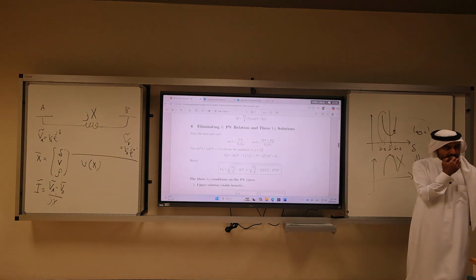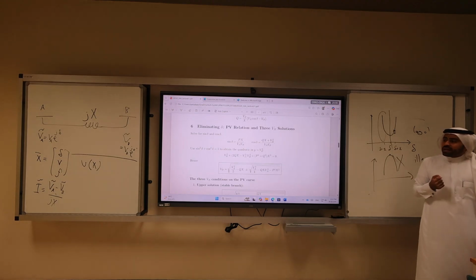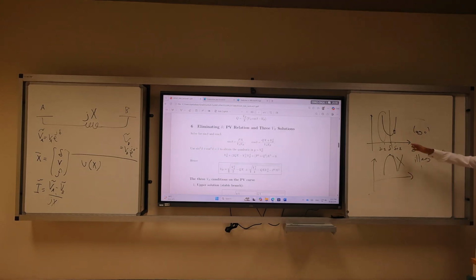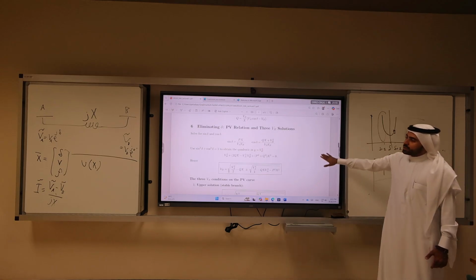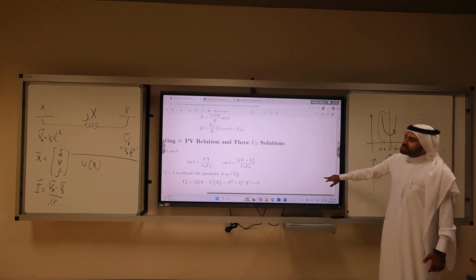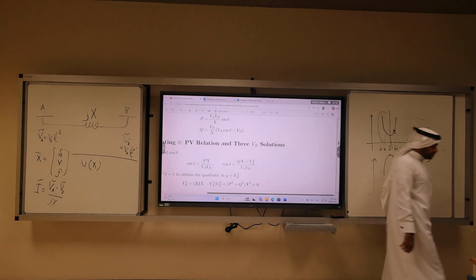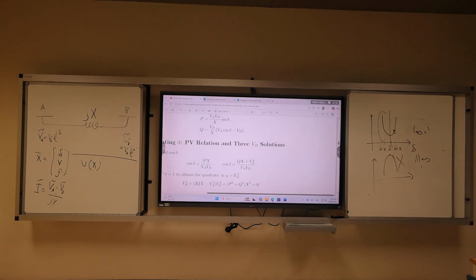Because sine 90 equals cosine. Well, if you operate above 90 degrees in this region, you still can go back to stability. But how can I answer this question? What is sine of 100? It starts having negative signs. Negative. So don't exceed 90. In power systems, there is no delta larger. If you're above 90, you're unstable.